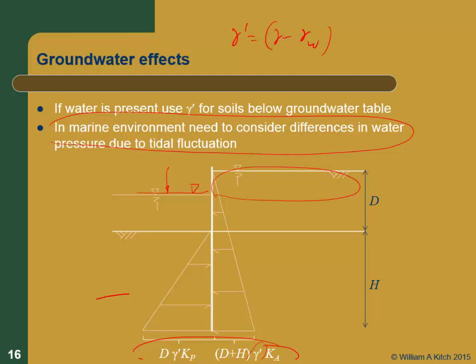Yeah. Sorry. If I forget that we have non-geotechs in here and I'm making too many assumptions, please ask like that. Yes. So your buoyant unit weight is just the saturated unit weight of your soil minus gamma water, the unit weight of water. Thanks for asking.